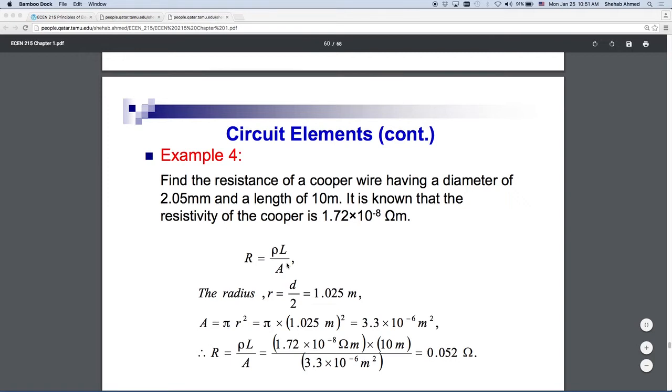They need to be low resistance, because otherwise we will be burning all this power that we're transmitting through the power system here. So in a distribution system, we don't have an option. We have to live with smaller wires because we have to put them behind the walls, under the ground, above the ceiling. So we cannot have all of these lights, for example, fed from huge diameter cables because they're low resistance. So it's a cost issue, it's a weight issue that we cannot basically work with.